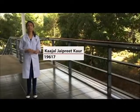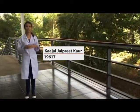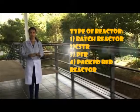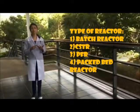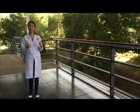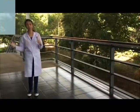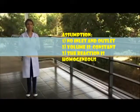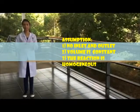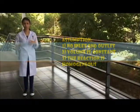In industries, there are many types of reactors, but the four main reactors are the batch reactor, CSTR, PFR, and also the packed bed reactor. In our experiment, we used the batch reactor. So, the assumptions for using the batch reactor are, firstly, there is no inlet and also no outlet flow. Second, the volume is constant. And thirdly, the mass is homogeneous throughout.